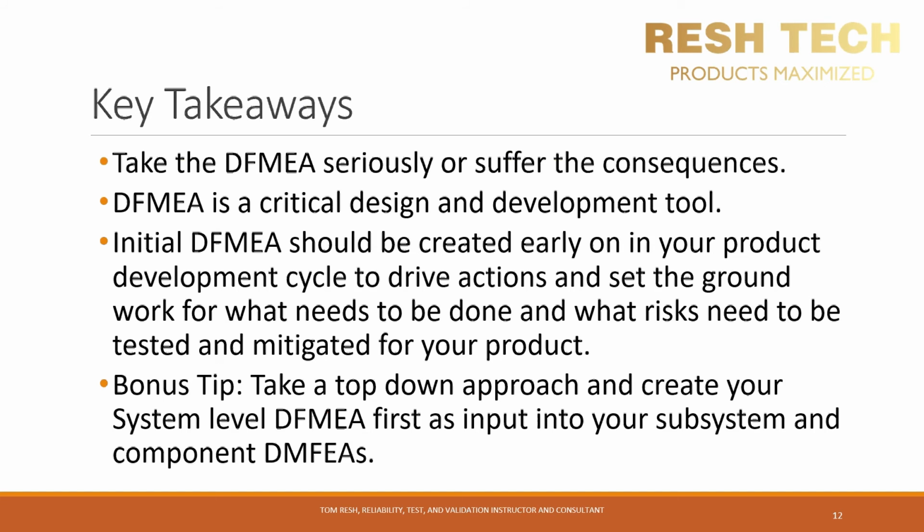Use the risks you identify in your DFMEA to help you design a better product. The initial DFMEA should be created early on in your development cycle. Don't wait until your boss asks for your DFMEA to scramble and throw something together to keep him or her happy. Start thinking about it and jotting down your risks early on so that you have a head start in developing your product design.